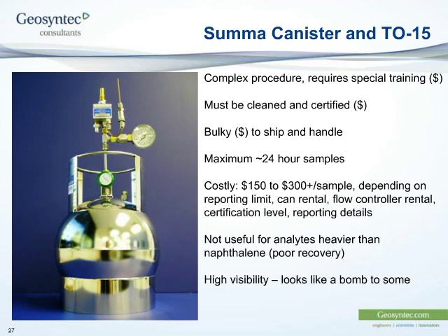Okay, do you see the SUMA canister slide in front of you? I do. Okay, so next slide. I mentioned earlier that SUMA canisters aren't necessarily the simplest thing. The procedure is fairly complex with a lot of wrenching that needs to happen, and if the wrenching isn't done to the right pressure, there can be leaks. And there is some special training that's required to make sure that valves get on properly and vacuums are measured correctly. They need to be cleaned and certified, which costs money. They're bulky and expensive to ship and handle.